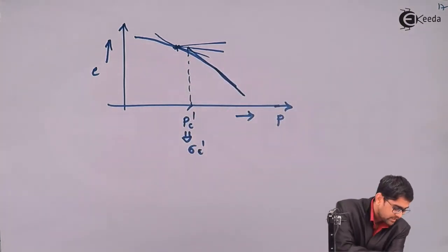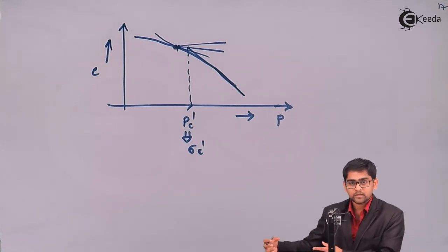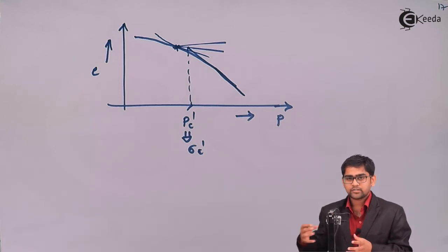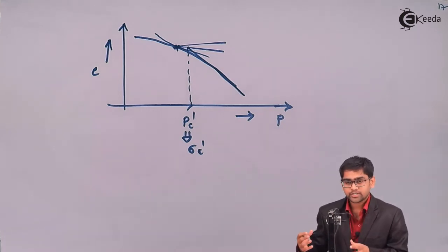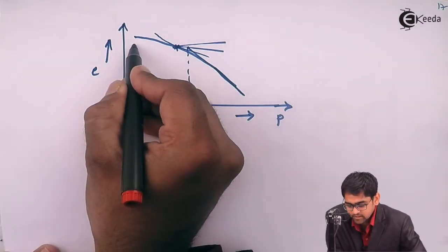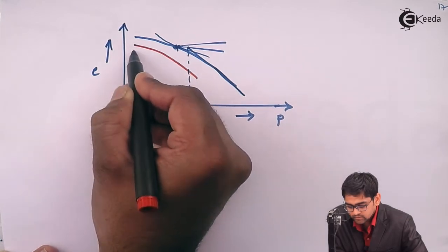This procedure is given by Casagrande. But what happens in many cases is that you take the sample in the field and test it in a lab, so there are disturbances, there is a loss of moisture, and there is a kind of remolding effect that the sample will experience, because of which the curve will become like this.